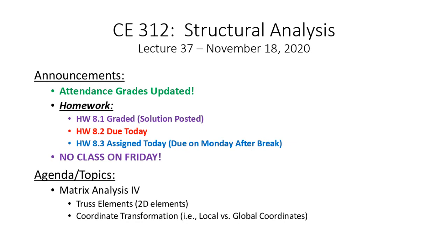For example, one of the strategies that computer programs use internally is they'll number the nodes so that all the fixed boundary conditions are numbered last. Then all they do is strike out all the rows and columns at the end, instead of what we did, where we struck out rows 1 and 4 and then columns 1 and 4 and kept 2, 3, and 5. But we only have a little bit of time. My main purpose on the assignment was making sure that you understood that assembly process, how each element's value went into the matrix at a particular point. That's really what I was after.